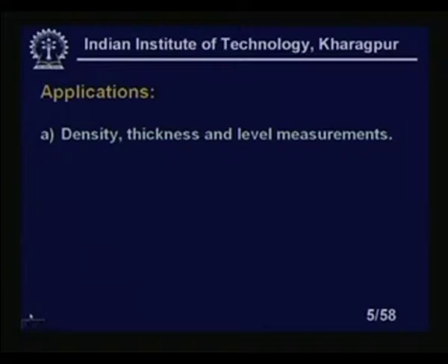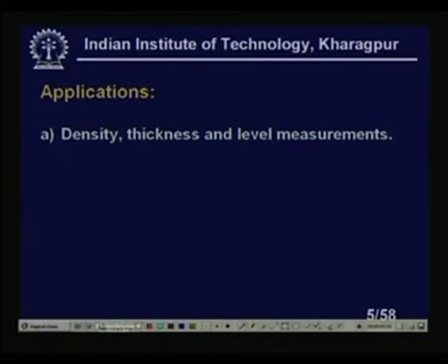Even though we can make data acquisition and store the data in computers, people always want some hard copy also. If you want to store that type of signal, suppose I am recording temperature signals over 24 hours with a sampling of every 10 minutes, I want to record that temperature on a strip chart recorder. One method is to use a strip chart recorder with a thermal stylus, where the thermal stylus will move and the recording looks like this. That means, let me take a blank page. So, I have a strip, it is moving, right.